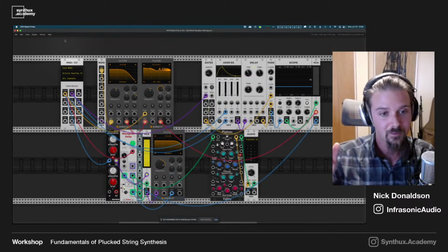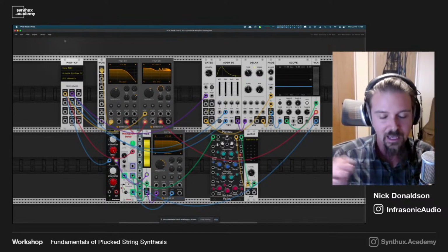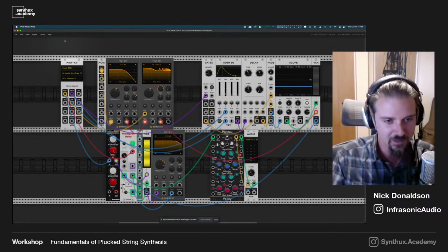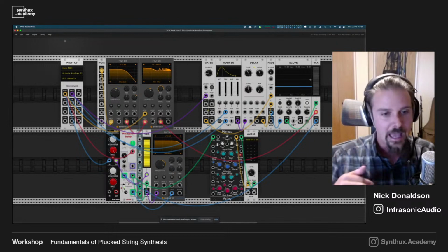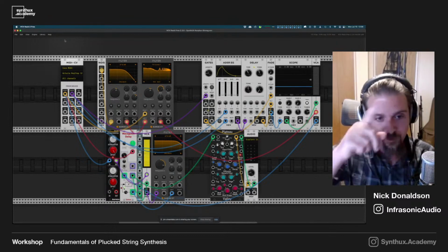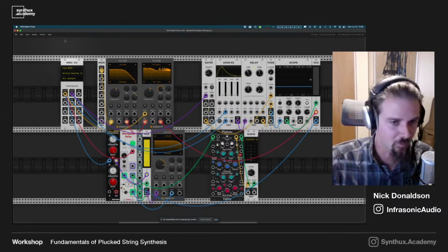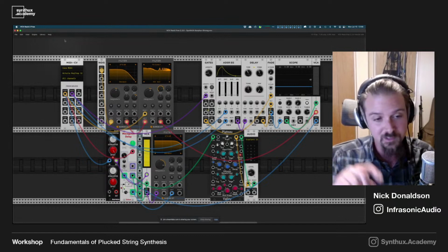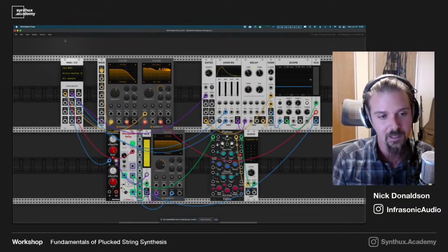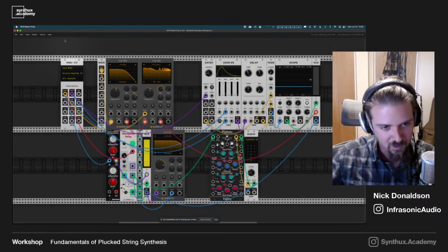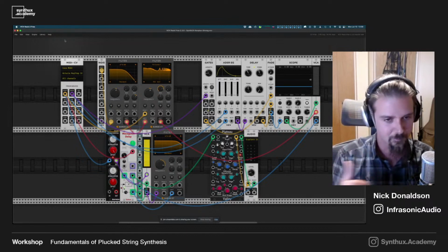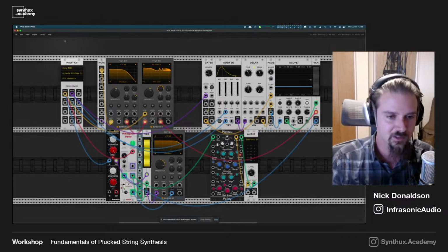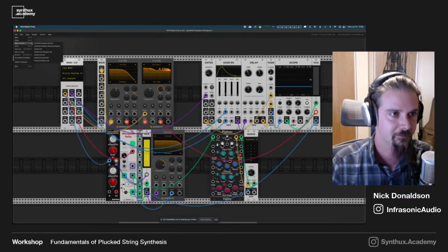And the energy, the partials in our spectrum of noise that fit directly into that feedback length, actually reinforce each other. So let's say there's some energy at whatever the fundamental is, that is going to build up itself. It's going to reinforce itself as we add it back into that delay line. Same with all of the exact harmonics. So multiples of the frequency, those actually add together constructively.